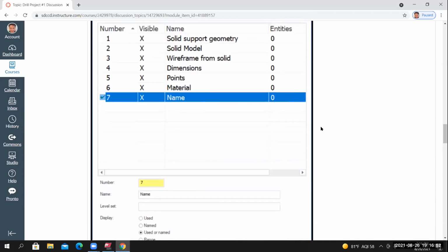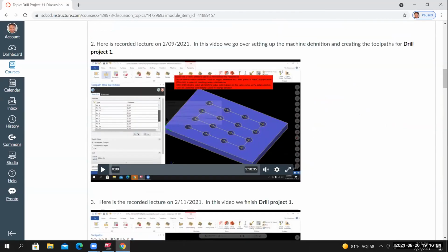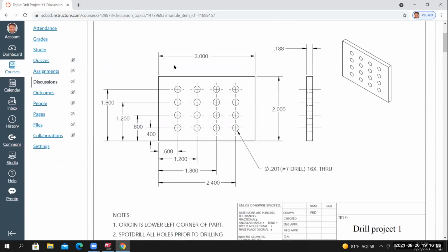I go back to the engineering drawing. We're going to create dimensions that are similar to the ones that you're seeing on the engineering drawing. They don't need to be exact. We're using this dimension tool to verify that our geometry is correct. We're not actually creating an engineering drawing. The dimensions in Mastercam, I use them strictly for verification of geometry inside of Mastercam.